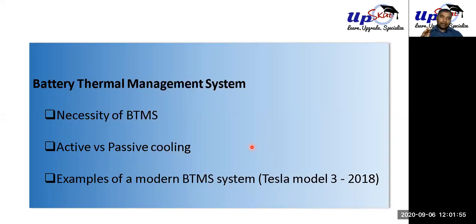The range a battery can survive is from like 40 to minus 40 degrees centigrade, but it will degrade heavily. The ideal range is from 20 to 40 degrees centigrade. But automobile batteries, which have the requirement to last 10 years or so, have an even more stringent requirement. We try to keep the battery from 35 to 40 degrees centigrade. In no case do we let it drop below 30 degrees centigrade.